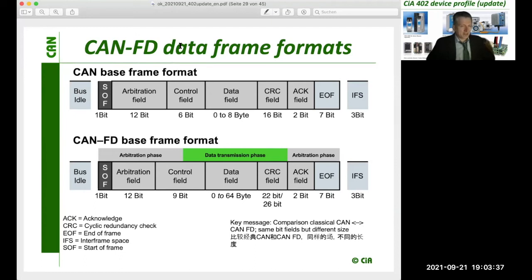Robert Bosch, the company developing that, said there is no need to maintain the same bit detection mechanism for each bit, which effectively limits my speed, but within a data transmission there is no need to do so. It can be transmitted with the highest speed supported by the CAN transceiver. By this means, it could be up to 100 megabit if the transceiver supports this functionality.